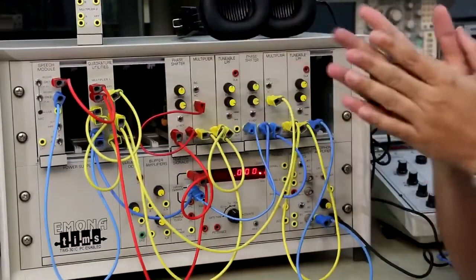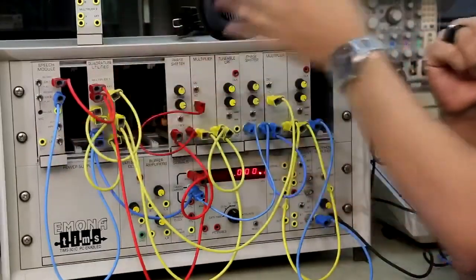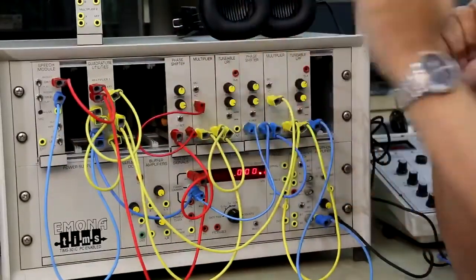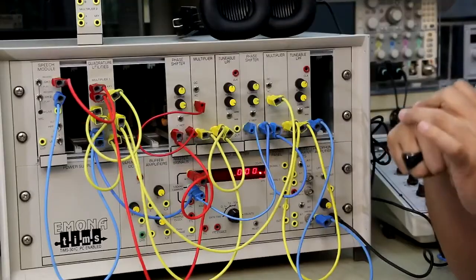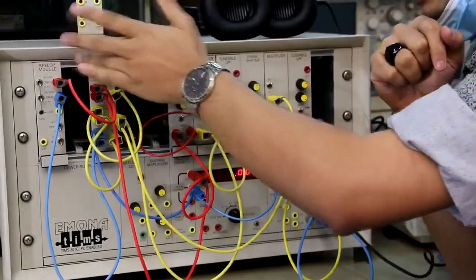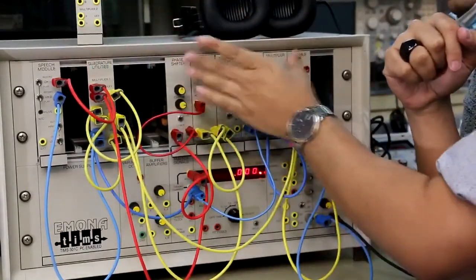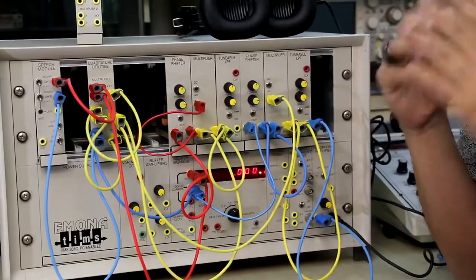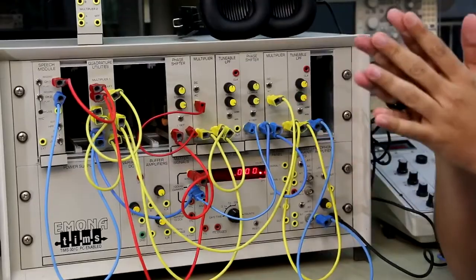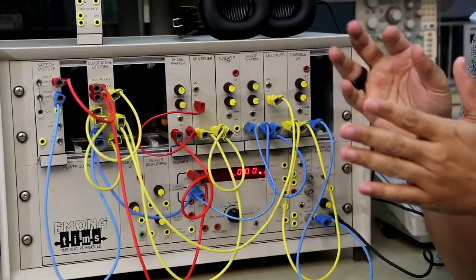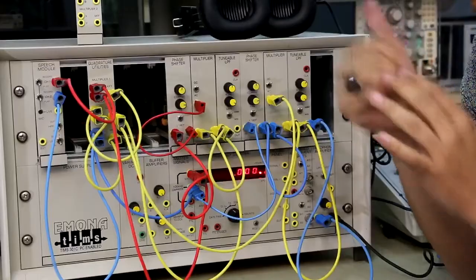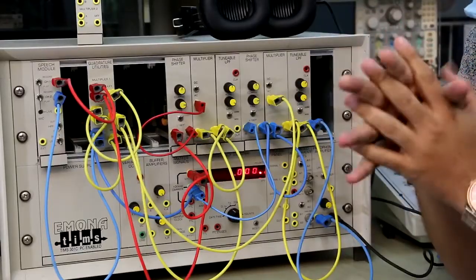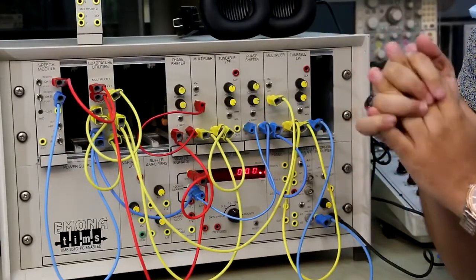But the whole objective is that you are sending two messages, and you are getting two messages back. There might be some difference, and that is because of the phase difference between the carrier used here and the carrier used on the demodulator side. So the more costly equipment you use that can fix even a small amount of phase error, the less interference you will have on the demodulator side.